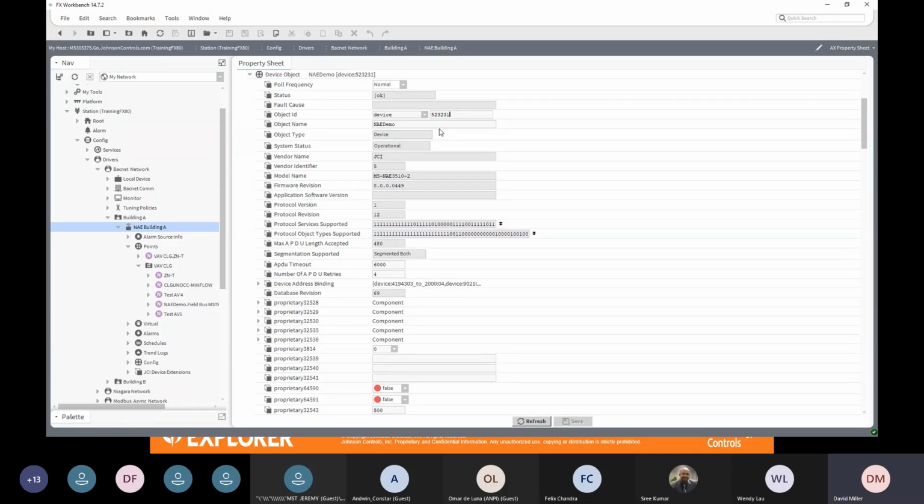The same device on trunk number 2, you'd make it 2025, and if there's trunk number 3, 3025, and so on. So you can have trunk numbers and then have device numbers. But at the end of the day, your device numbers need to be unique across the entire site.